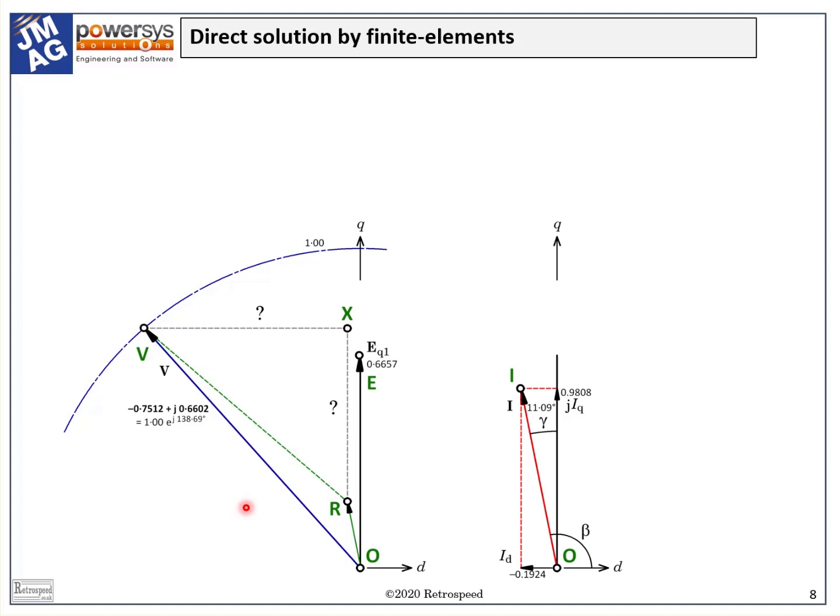The resolution of this question is interesting and I would say important. It depends on the way in which we approach the phasor diagram. If we start out with the assumption that xd and xq are constant and unaffected by saturation, we are likely to run into trouble, especially in a machine like the IPM or the wound field synchronous machine, in which the variation in these reactances can be very large. A common approach is to try to calculate saturated values of xd and xq. This approach runs into questions of uniqueness, as we will see.